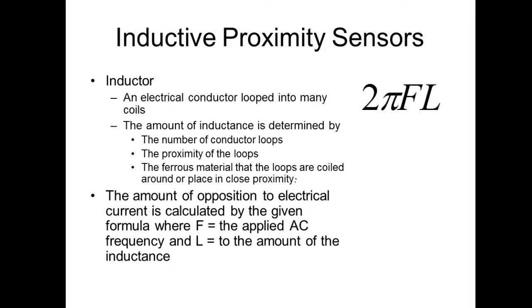Inductors basically are just the opposite of capacitors. So inductors are nothing but loops of coils of wire. That's all they are. If we put DC on these things, they act like wire. We put AC on these things, they act like inductors. And inductors react to frequency. So on inductors, if the frequency goes up, the opposition goes up.